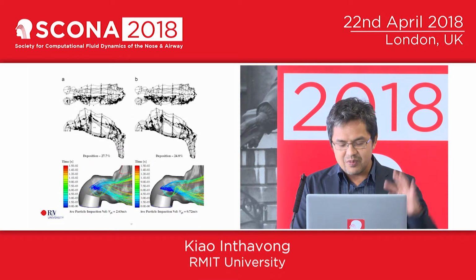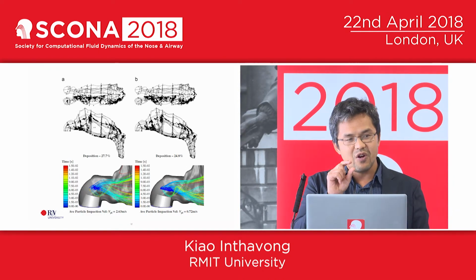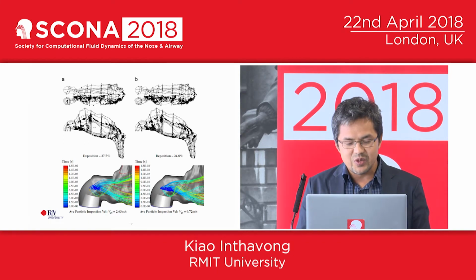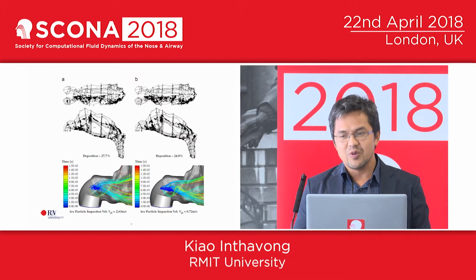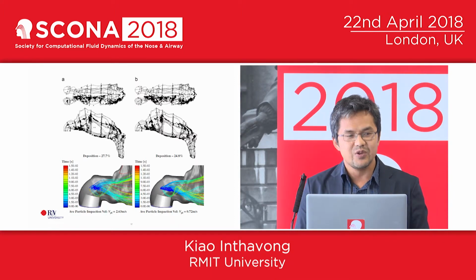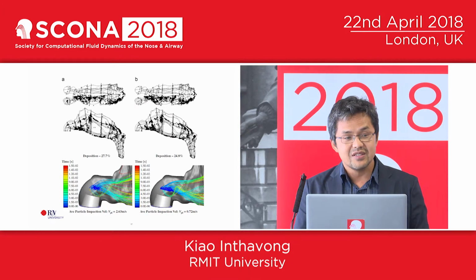And in the previous images, which I didn't talk about, there was a length from the spray nozzle tip to where the ligament breakup started to occur, and we called that the breakup length. So from where the nozzle was to where it formed droplets was the breakup length, and that region in between was just a liquid phase. So we introduced particles at a breakup length, 5 millimeters typically, above the nozzle.